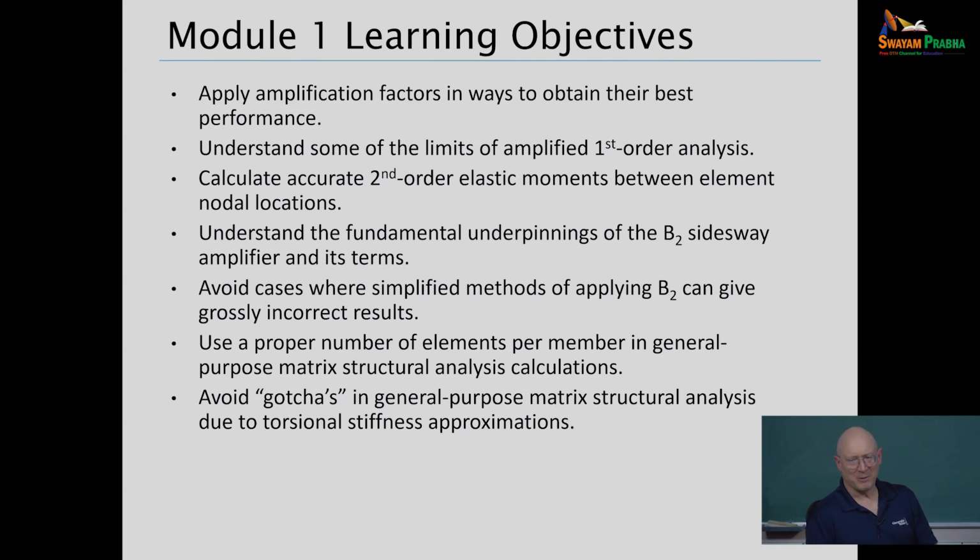With most of the software out there, Consteel basically surmounts all that, because everything they do is based on a 14 degree of freedom element with 3 translations, 3 rotations, and a warping degree of freedom at each node. That allows us, with thin-walled open sections, to capture the thin-walled open section beam theory behavior quite well, and that's the basis of our code provisions for a lot of the things we do.